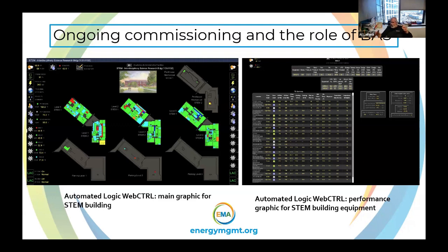For those on the call who don't know what a dual duct is, to keep it simple, you had one duct bringing hot air to a mixing box and a cold duct, and they had dampers, and it would blend. It was like the perfect system because you always got the temperature you wanted. There was never overcooling and never overheating. It was an energy pig, the only way to describe it, because you were always cooling down and reheating.